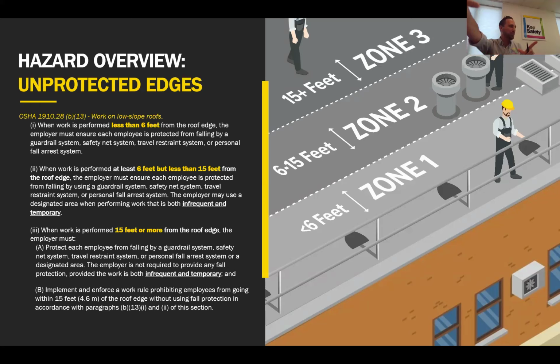Any units outside of 15 feet, you're allowed to work on. And we have temporary anchor points that we can move around the center of the roof, that if the project's going to take longer than what we think, we can use the anchor point. Or we corral in at 15 feet. We connect the corrals with warning line full perimeter. We have one temporary anchor point that we can move if for whatever reason we need to work beyond where that warning line is. You tie off, you go underneath, you do your work, and you come back, right? So those are some of the ways that we implement this plan.